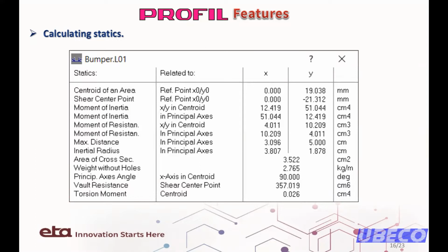Here, the statics of the profile is being calculated. Information such as moment of inertia, moment of resistance, area of cross-section, weight, torsion moments, and so on are calculated and can be transferred to the CAD system.